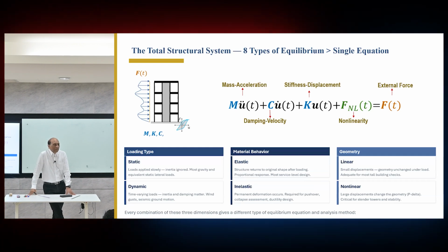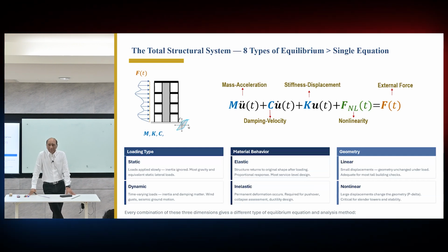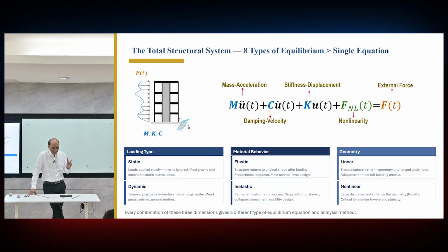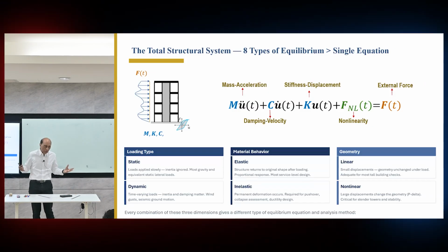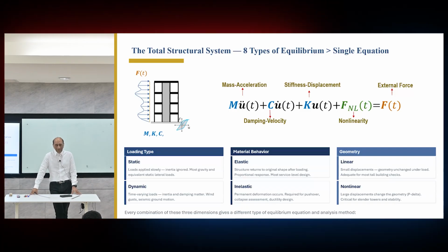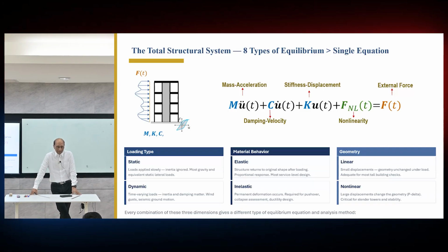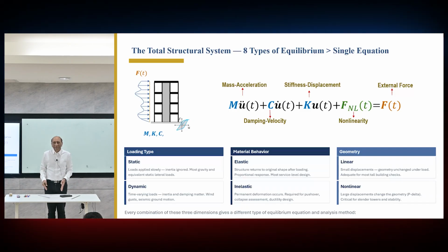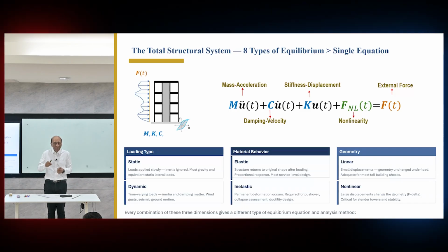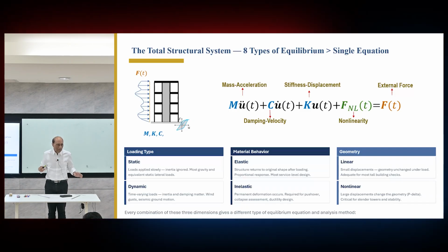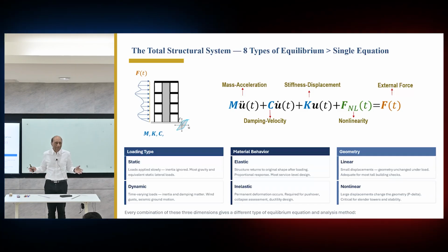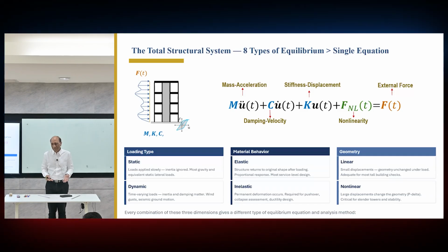This is the sum of all the damping in the structure. This is the sum of all the stiffness in the structure. This is the sum of all the forces applied. Sum, I mean accumulation, let's say accumulation, not sum, which is a matrix or a vector. So we put everything together into one big matrix or vector, not missing anything at all, and put them together as one set. And we say, okay, now we have the equation. It's just a little bit too big, fine.